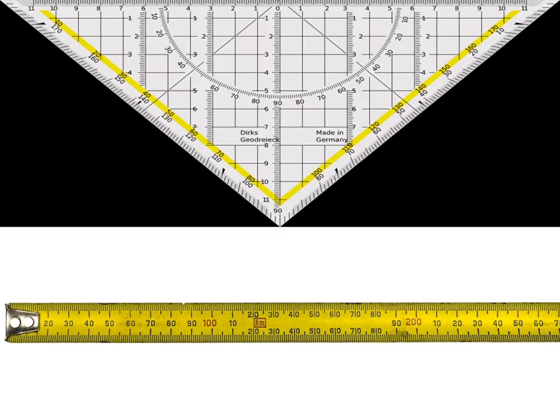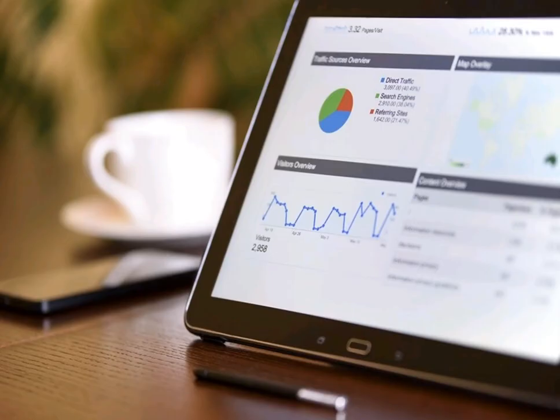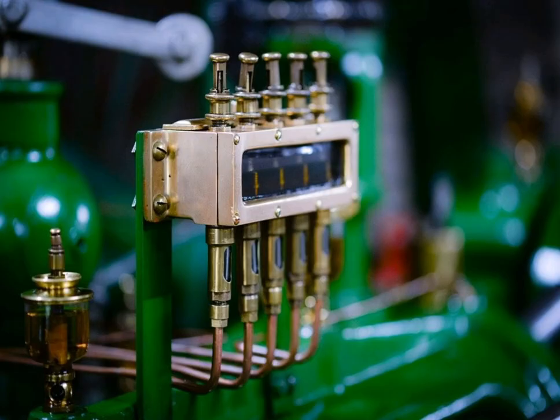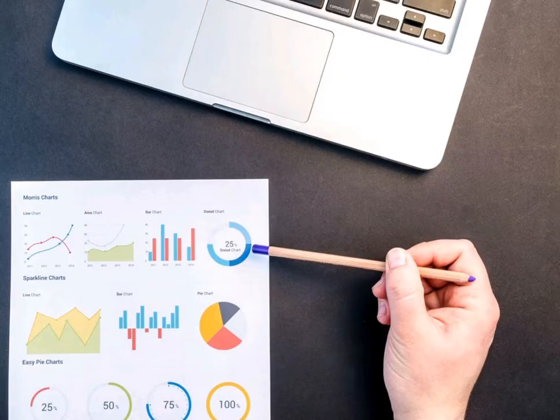Today manufacturing companies gather massive amounts of information through measurement and inspection. If there are errors in our measurement system, we will be making decisions based on incorrect data. We could be making incorrect decisions or producing non-conforming parts. A properly planned and executed measurement system analysis (MSA) can help build a strong foundation for any data-based decision-making process.